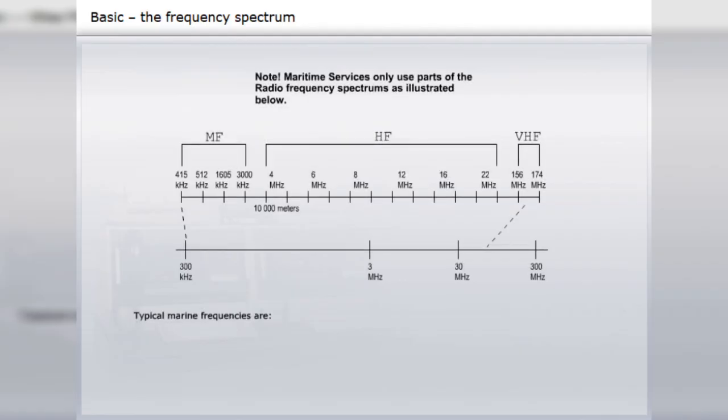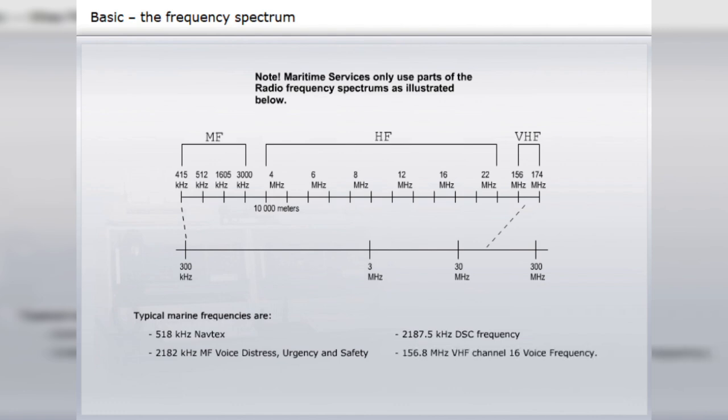Typical marine frequencies are 518 kHz Navtex, 2182 kHz Voice Distress, Urgency and Safety, 2187.5 kHz MF-DSC, 156.8 MHz VHF Channel 16.